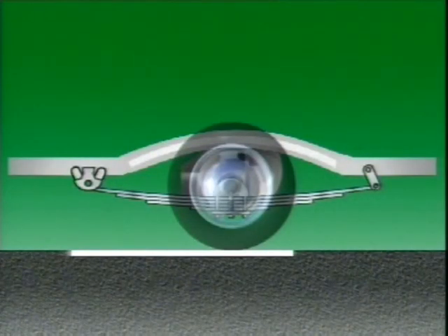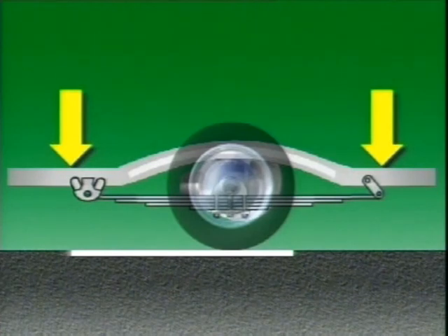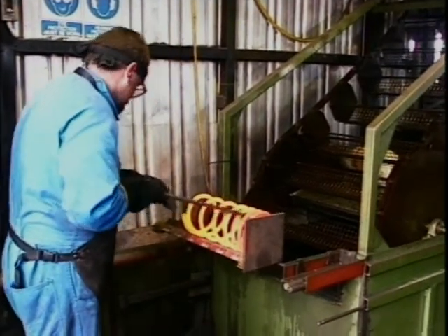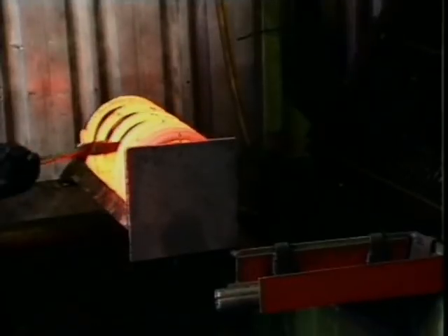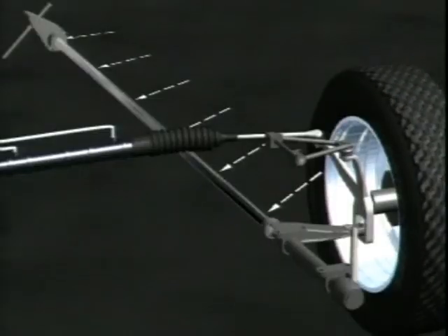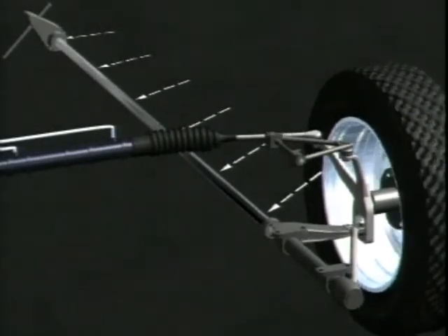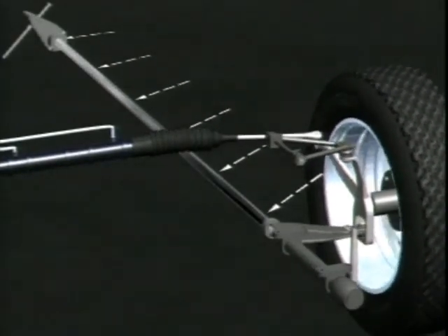Leaf springs are normally semi-elliptical and they absorb the applied force by flattening out under load. Coil springs are formed in a spiral from a single steel rod and absorb the force of impact by twisting. Torsion bars are held rigid at one end and twist around their center as the suspension arm is deflected. They all